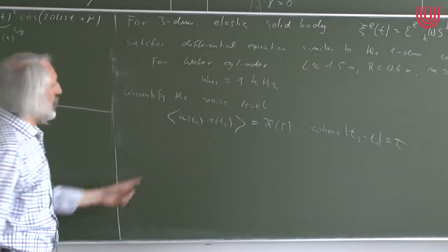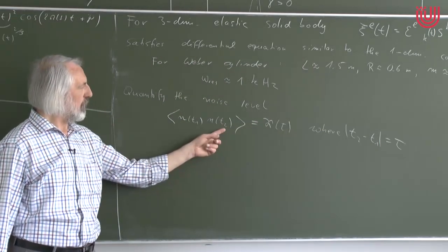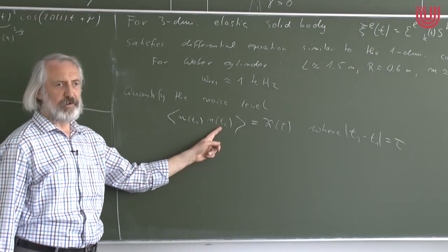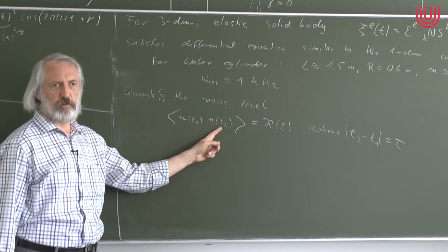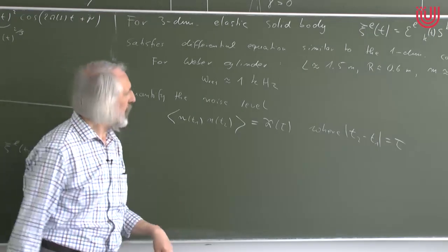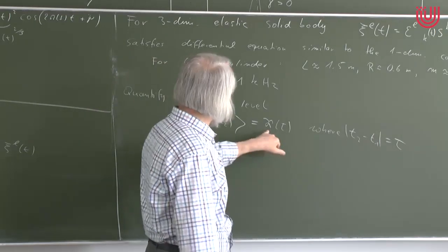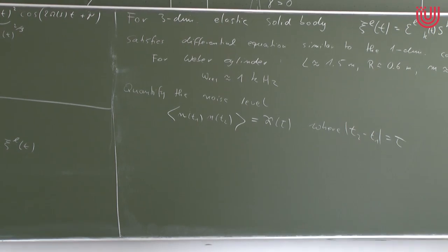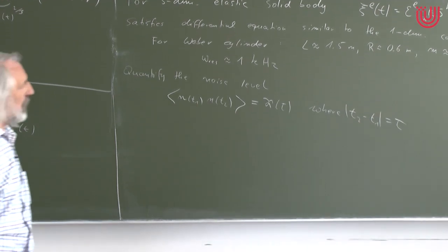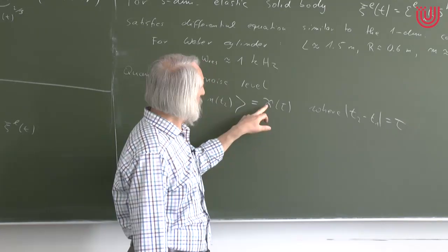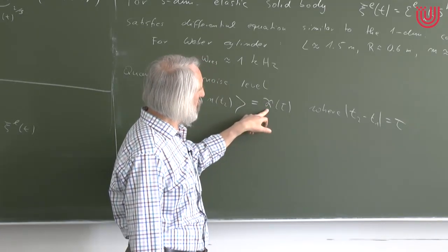If I do it now and 5 hours later, or tomorrow at the same time and 5 hours later, I should get the same probability of seeing any signals, if I have just random noise. This kappa is what is called the autocorrelation function of the noise signals. And now we want to know how the signal depends on the frequency.